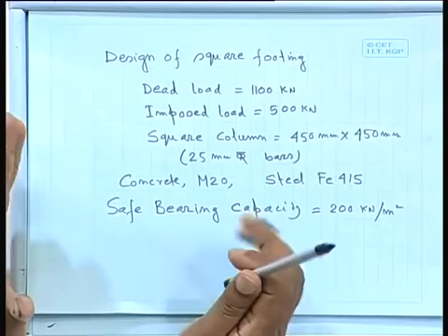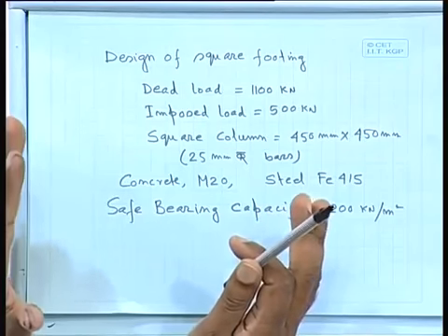Say the span of the bridge, if it is less than your live load or vehicle load, because that is the objective for making a bridge. So the vehicle load, whatever is coming, and the dead load of the structure of the bridge, for a small span, maybe, say, 20 meter, or you can consider 15, 20, 30, like that, that is almost 1:1, something in that ratio. But if it is more, maybe 100 meter, then you will find that the vehicle load is very less compared to the dead load.